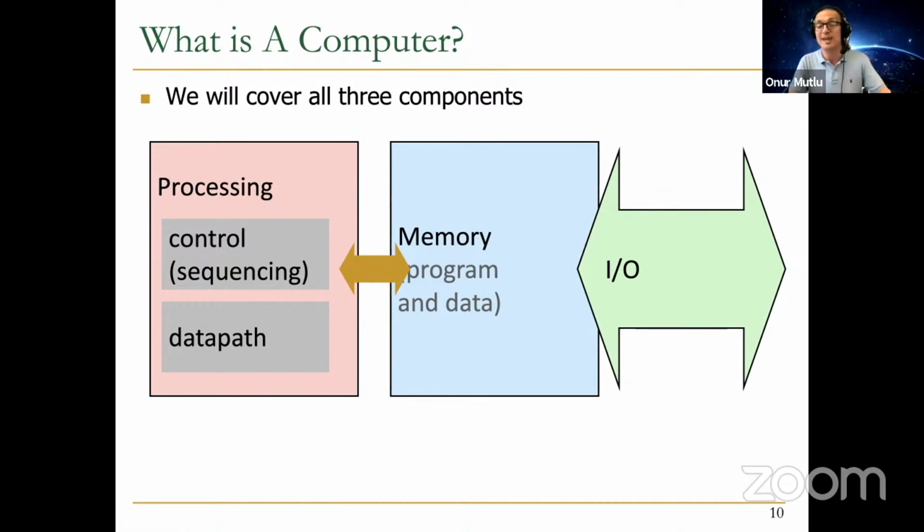So you may actually be accessing memory in a much more irregular manner than we are doing today in GPUs, for example. GPUs are very good at accessing memory in a streaming manner so that you can exploit the high memory bandwidth, but memory systems are not designed for random access in general. So that's a very good question. I think the combination of these processing paradigms and memory is also important to examine in terms of trade-offs.